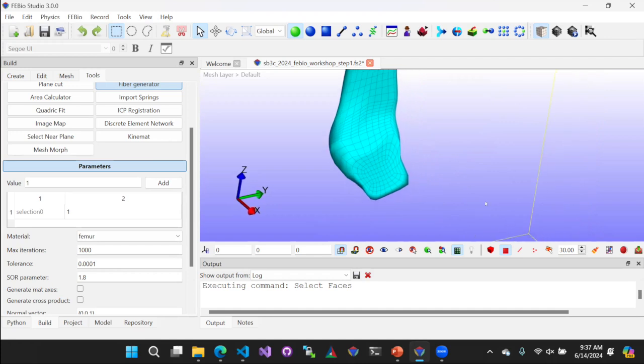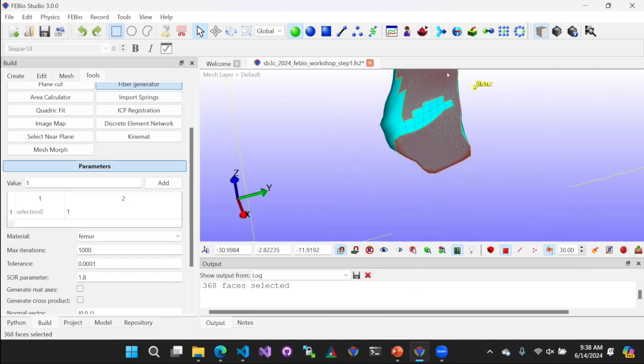making a selection. So there's also a button here called Select Connected. So right left of this 30 here, there's a button. If you click that, what's going to happen now, if you select anywhere on your model, it's going to select all the faces that have a surface normal that is within 30 degrees of the surface normal of the facet that you clicked on. Now, as you can see, that kind of bled through the boundary that we wanted.